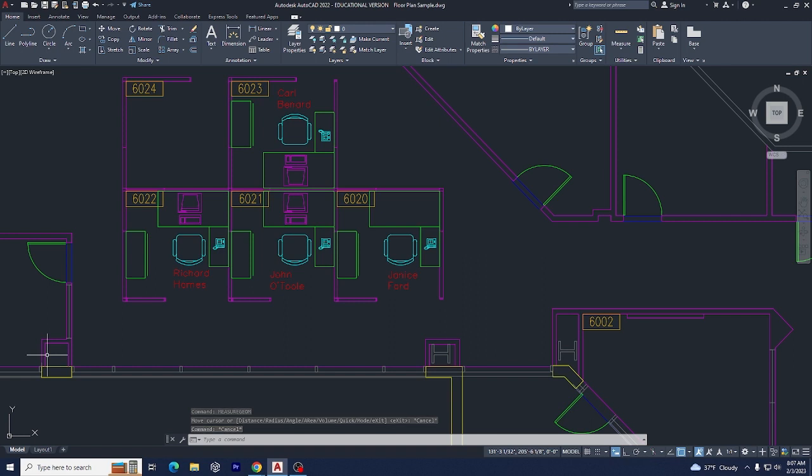And the area option of measure geom can be used to subtract areas or holes. Like we could measure this, but get rid of all the extra stuff in there. So measure geom can be used with subtracting stuff as well, which is really cool if you're trying to do some quick measurements.